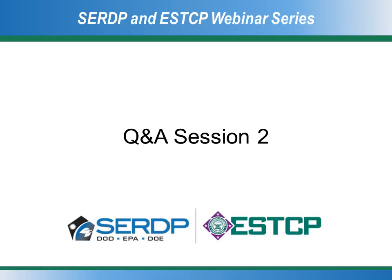Great. Thank you, Judy. And one last question for you. There was some lack of clarity about the resistivity contrast that is minimal to expect success, assuming conditions and survey design are suitable. Can you just repeat what you said with regards to the resistivity contrast, please? Sure. It's best to have the highest contrast possible, but I would say a conductivity contrast of about 10 would be suitable.